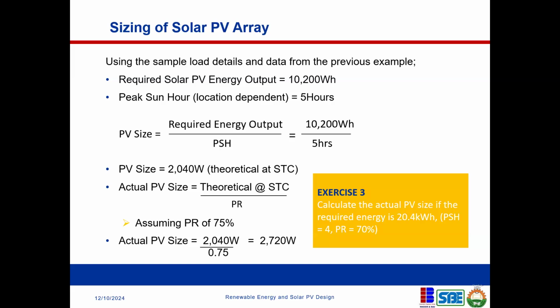Exactly. So divide this by the capacity of the panel that you find in the market. Then you know the number of panels that you need. All right. Okay, yeah. Thank you so much.